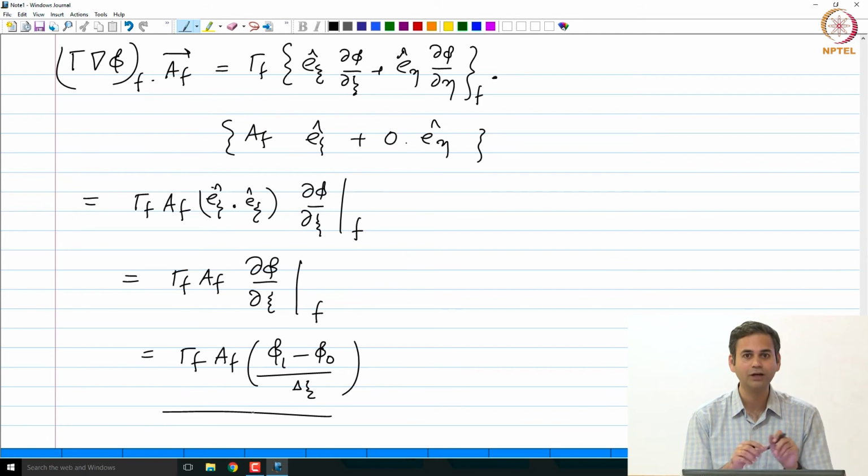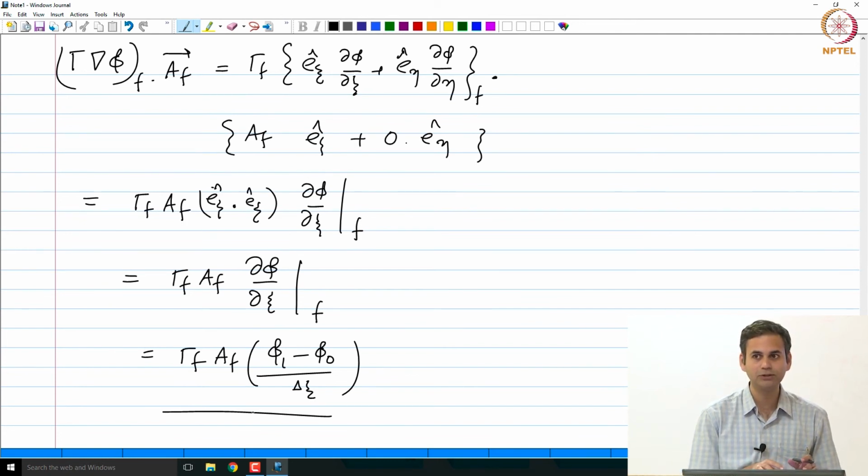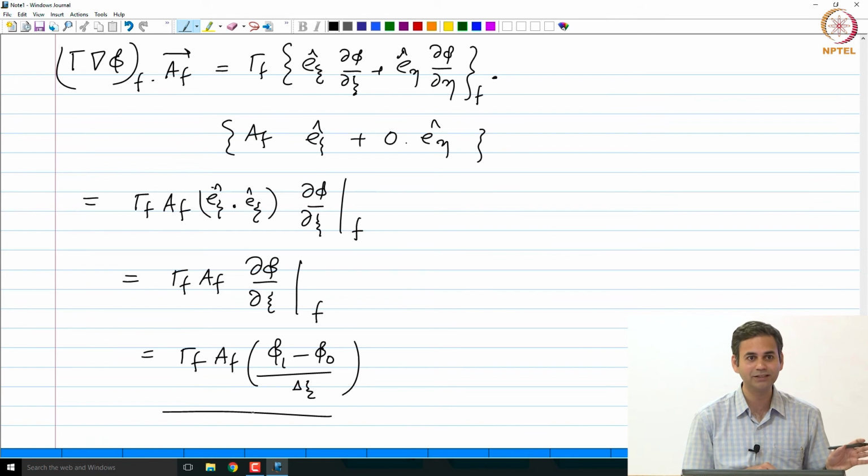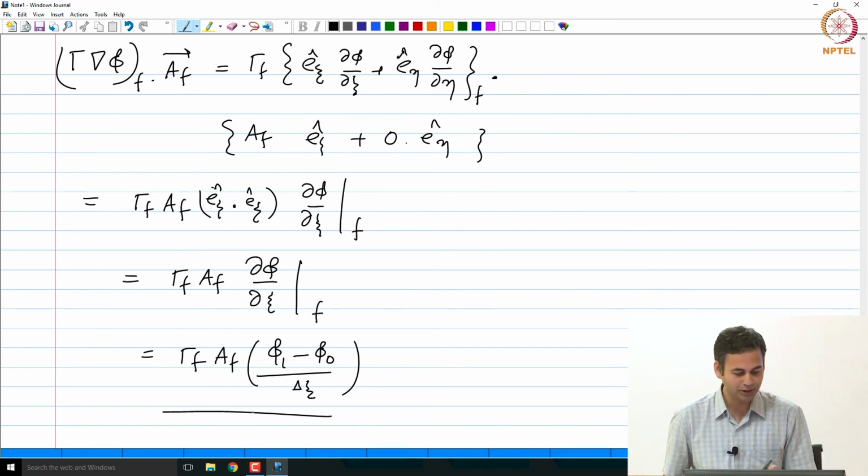So, that is why we introduced a local coordinate system for every face, and now we are calculating the gradients using the cell centroid values on this local coordinate system. Okay. Now, do you see a correspondence to the original Cartesian mesh case? What did the Cartesian mesh coordinates used to look like? What did the coefficients look like?